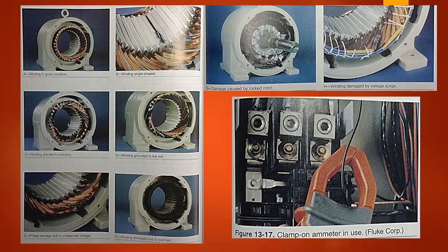Bearing wear in motors can be identified by sound, vibration, or excessive heat at the bearing housing. Large industrial motors have temperature monitors made from thermocouples to monitor bearing heat and windings. These monitors provide an accurate prediction of motor failure and allow the technicians to safely shut down the system and replace bearings or windings before failure occurs.